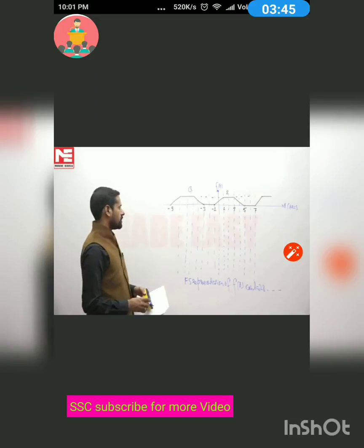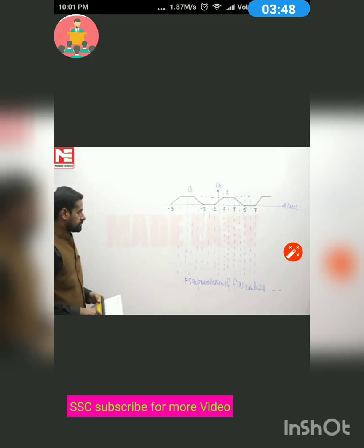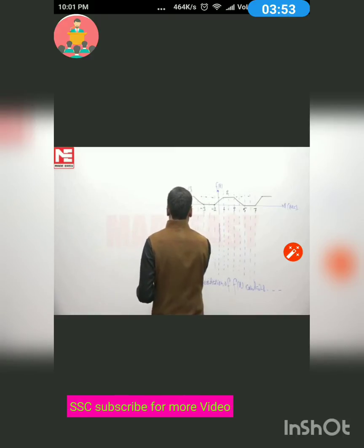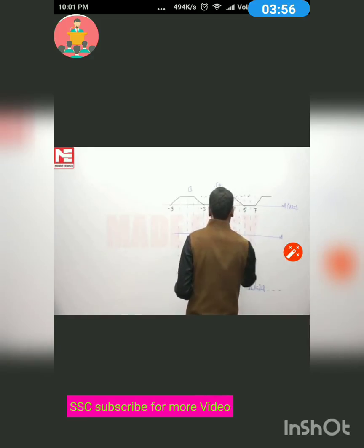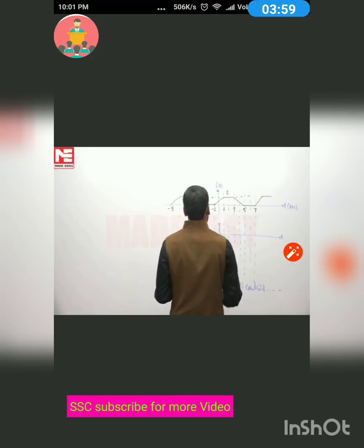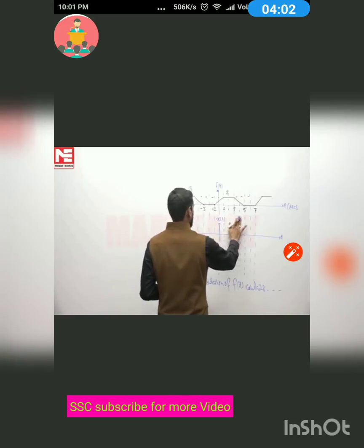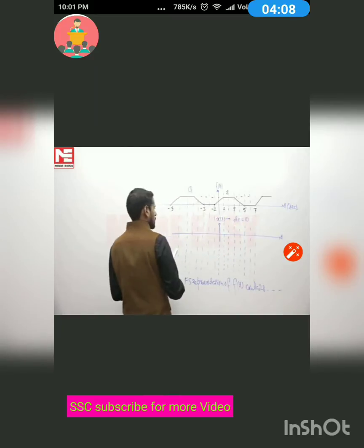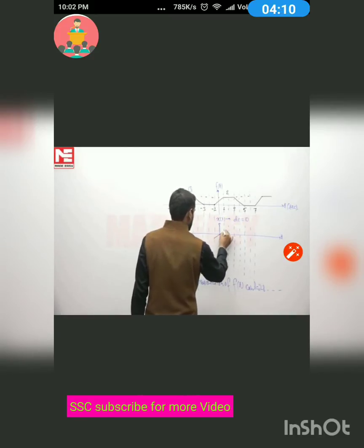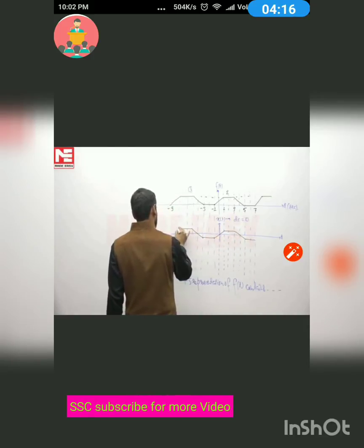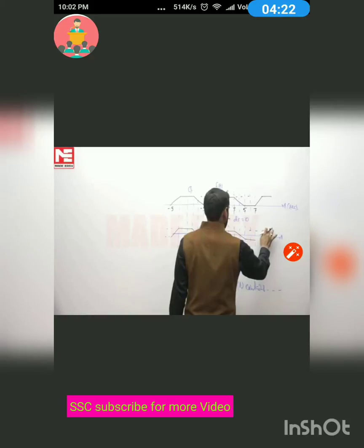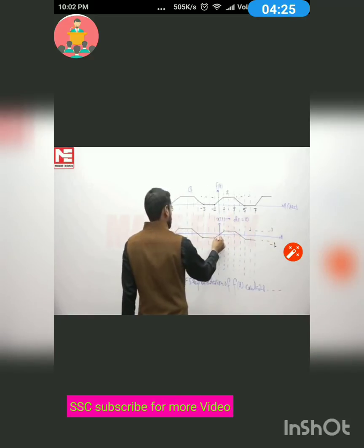In the next question, we have to find out the Fourier series representation of signal f(t). First of all, by looking at this signal, we will draw another signal which would have 0 DC value. So we will draw a new signal x(t) with 0 DC, and if we draw this signal, it will look like this. The amplitudes will be +1 and -1 at the same time instants.